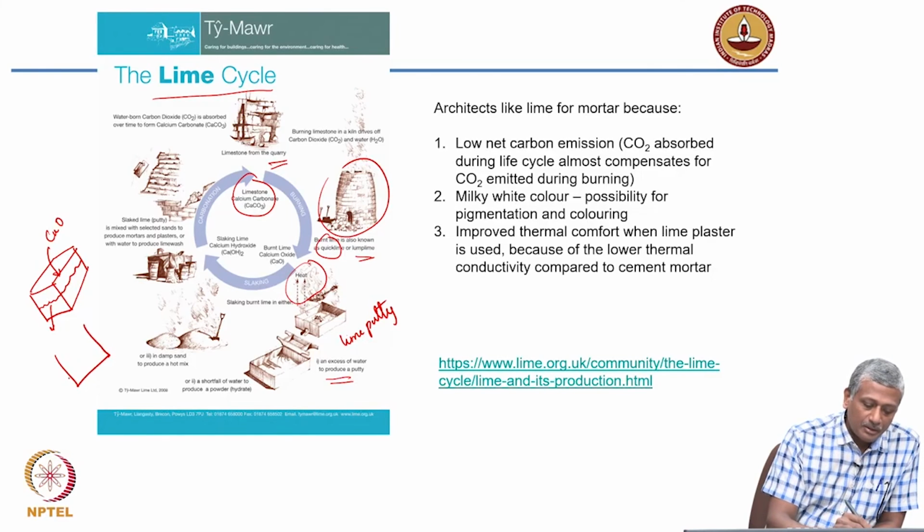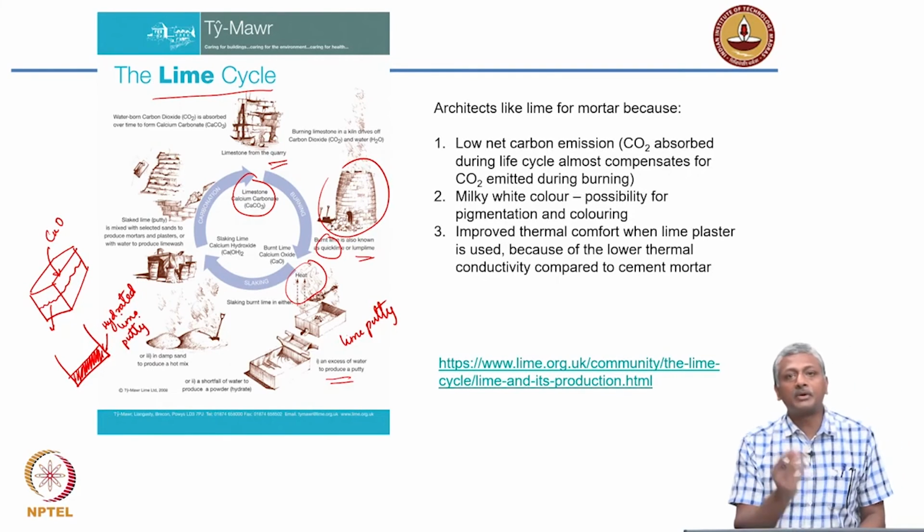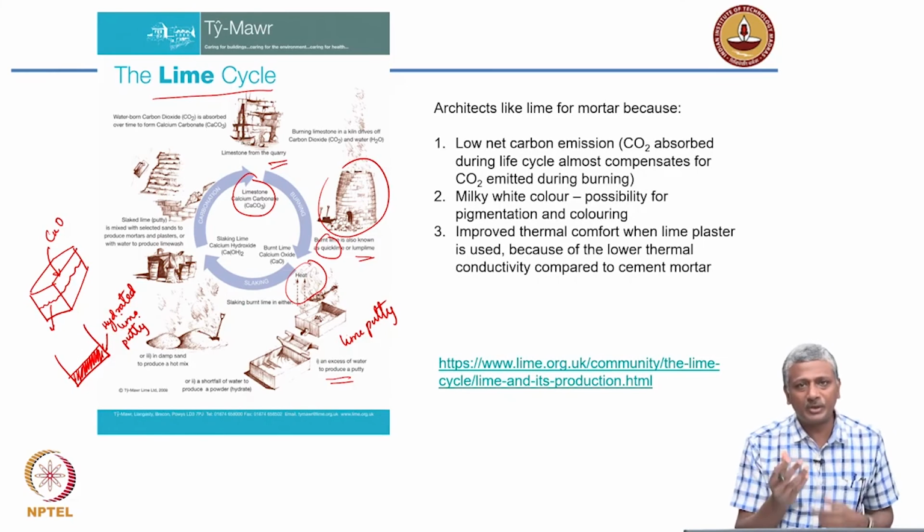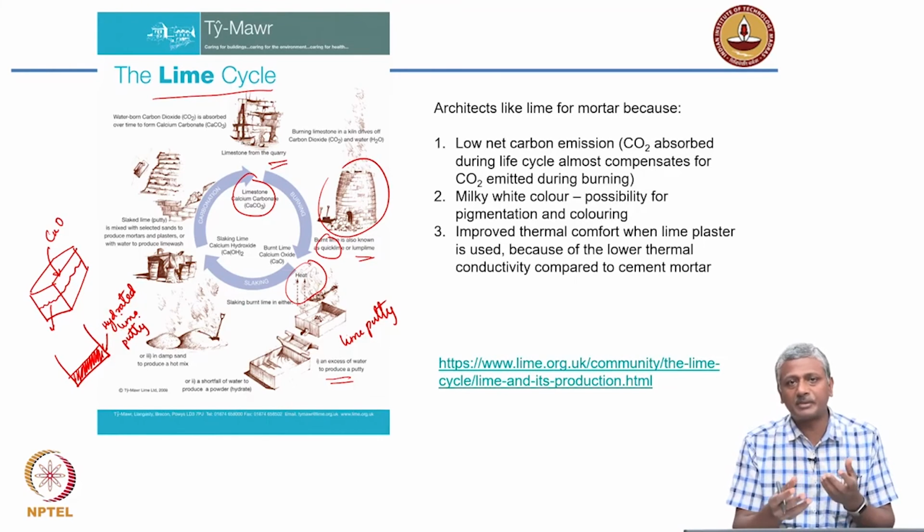At the bottommost part, you form a nice plastic hydrated lime. All the lime gets hydrated ultimately, but what is at the bottom is called lime putty. Lime putty has a nice plastic nature about it, and you can mix it nicely with mortar, maybe sometimes add some extra water to make your lime mortar.